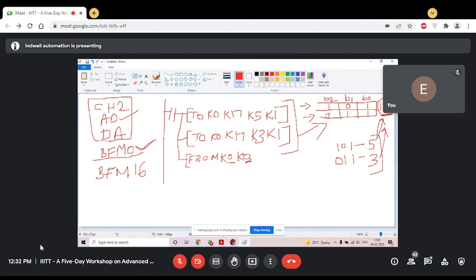After receiving it, I shall store that in some PLC memory, that is D0 or D1, whatever you have taken. So I take D0 here, so here is D0 and K1. Up to this, we have done channel selection, AD start, DA start, and third is the converted digit from BFM 0 taken to D0. This D0 I can give to HMI SCADA, and you can see temperature and other things there.